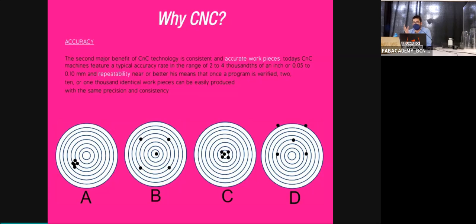You didn't attach your end mill properly, you didn't tighten the collet, you didn't put your material properly, you forgot one of the steps like setting the origin, etc. There are millions of things that can go wrong, and it's about the workflow of the machine. So a machine always has high repeatability and high accuracy.